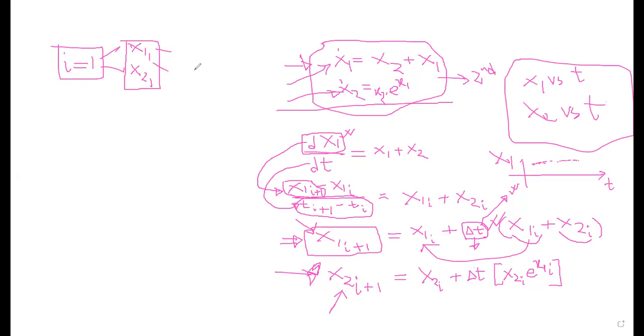And for SMIB, we have already done it. So we don't have to bother about the initial value calculation anymore. We know these values now for our SMIB system. But for solving this second order system, you have to know x1 and x2 at the first iteration. Once you know these, you can calculate the second value. Once you know the second value, then you can go for the third value and so on. Another thing that you have to set is the total simulation time, for how long you are going to simulate the response.